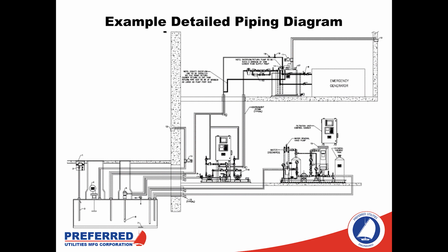Now, I like to refer to this as a fuel polishing skid rather than simply a filtration skid. We're doing more than just removing particulate from the system. We're also removing water, which is the largest driver of fuel oil quality degradation for stored fuel.